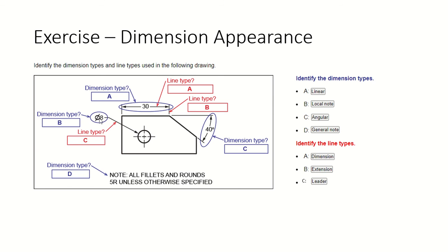And here your dimension type is a note, because that's what we call it. And here is your angle, of course, between this plane and that plane. You have to try to look at this plane extended to the outside, like imaginary. You suppose that this plane can extend all the way out, even though there's no material part in there, of course. So that angle is 40.